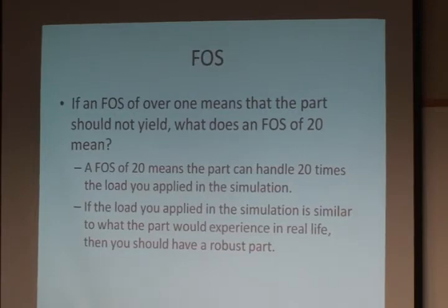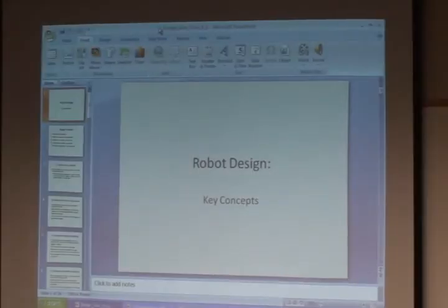One thing you guys got to remember is that the FOS is giving you a different force than what you're going to get whenever a 20,000 RPM beater comes and hits you. That impact load is a different measurement than what FOS is. So go heavy. That's kind of my advice. If it says it needs to be 10 and you make it 10, well, whenever Plumb comes at you with a 20,000 RPM beater and hits you and it bends, you're going to say, why did it bend? And it's usually because you didn't go 20 instead of 10. So beef it up a little bit.